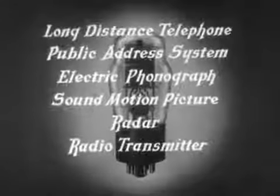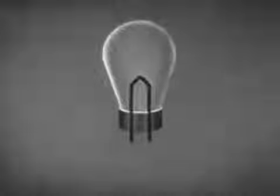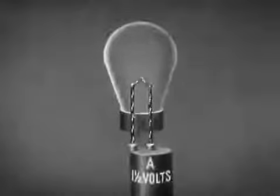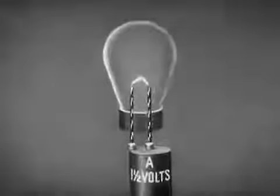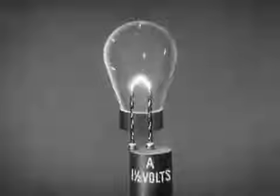Radar, radio transmitter, and radio receiver. First, let us consider how a three-element vacuum tube, the triode, operates. A tungsten filament extends into a tube such as this. A cell supplies a current which heats the filament. When the filament gets hot enough, electrons are emitted.